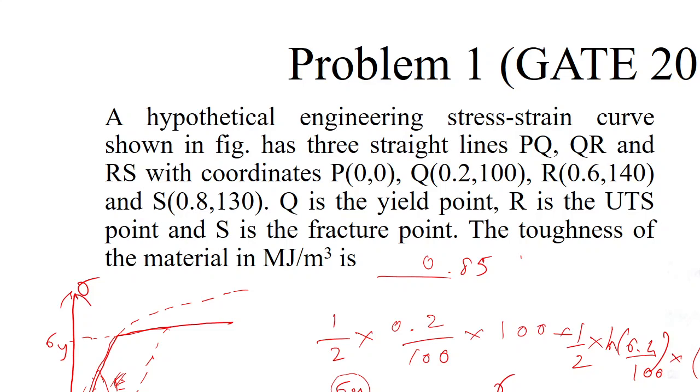Suppose I have reached up to this point, and then I remove the load entirely, all of a sudden, or gradually. It won't stay at this point; the final dimensions of the specimen won't stay here. Rather, it recovers some of the strain, because in the material both the elastic as well as the plastic strain is stored.